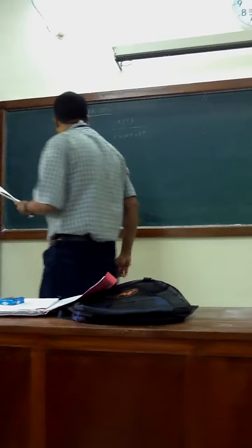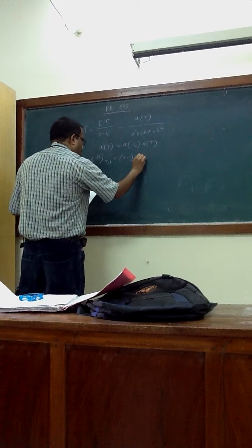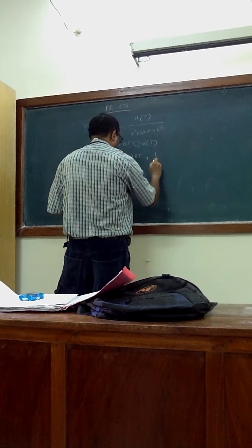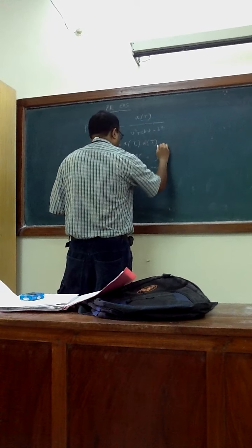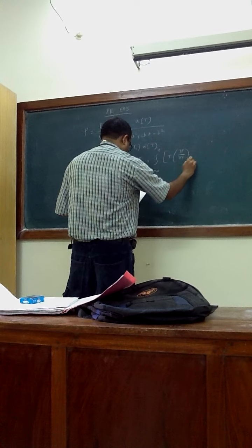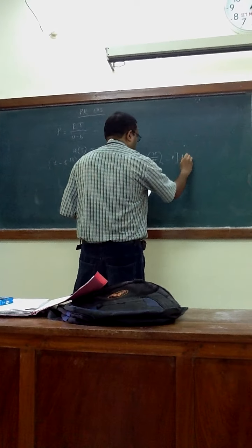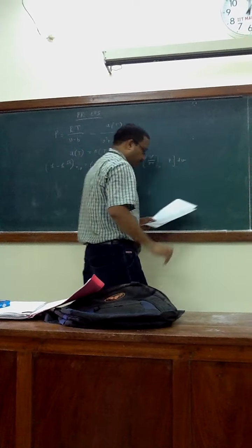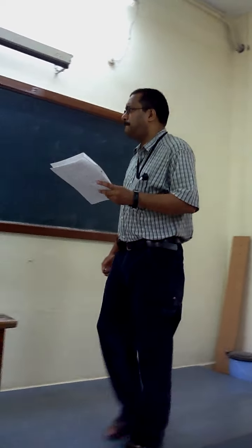alpha(T). Okay. So we know our formula, enthalpy departure, which is H minus H^IG at T, P, which is Z minus 1 RT plus the integral from V going to infinity to V of T dou P by dou T at fixed V minus P dV.